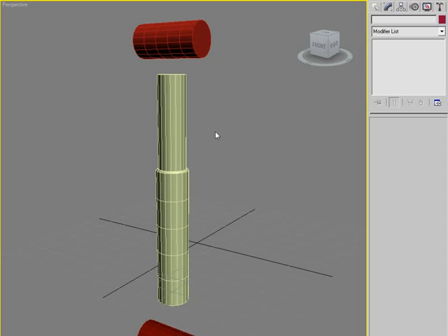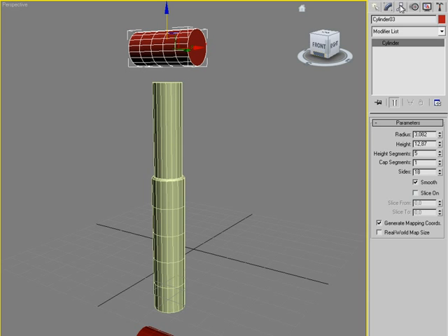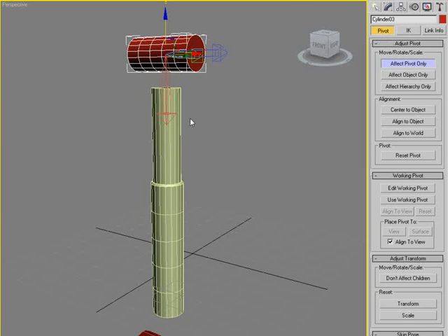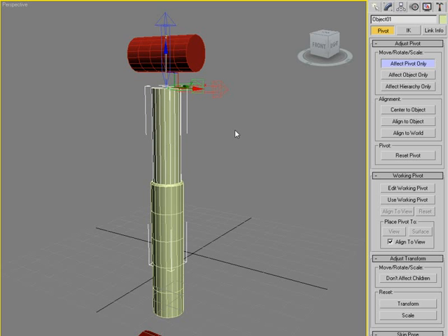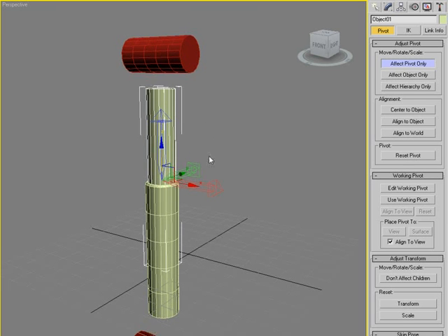So to begin with, we have to make sure all pivot points are placed correctly. So we select this one, and we're going to check the pivot point of it. And now it's centered by clicking here to the object, and that's where we want it. So now we check this one, and if you just start it over, say center, we need this pivot point to be at the top here, and not just around the top. It has to be exactly at the top for the best rigging.